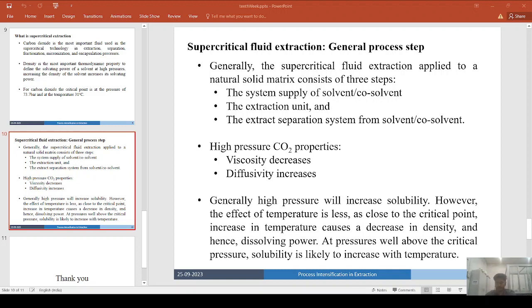There is another aspect. What about subcritical extraction? So, supercritical versus subcritical extraction. Supercritical extraction, being a much stronger solvent than subcritical carbon dioxide, allows for faster and more complete extraction. By the supercritical method, the lighter oils as well as not so desirable higher molecular weight materials such as waxes, paraffin, lipids and resins can be extracted. These fatty waxes will then need to be removed from the extract by a process called winterization.